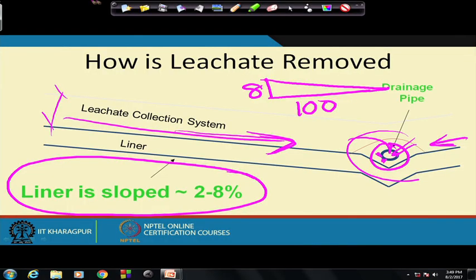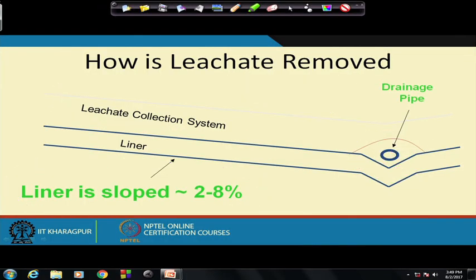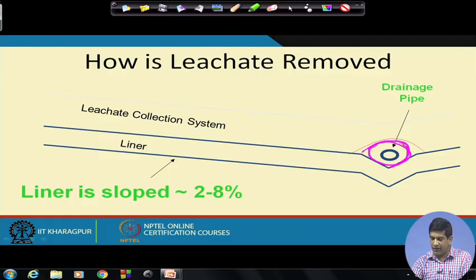And then it will get connected to these pipes, and the area over here will be filled up with some sand kind of material. The reason for that, and this is a geotextile. The line that you see on top is actually a geotextile. A geotextile basically acts as a filter. So this thin line that you see is a geotextile that acts as a filter.